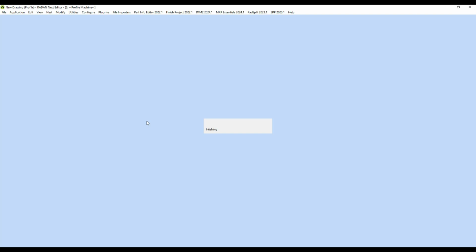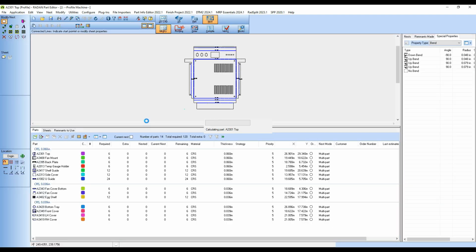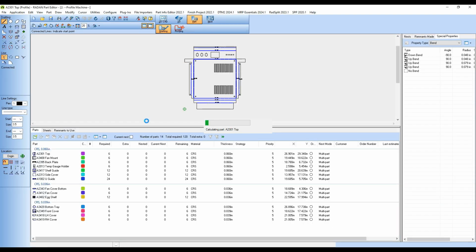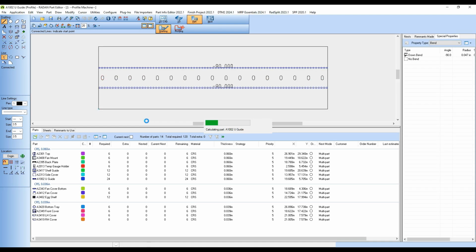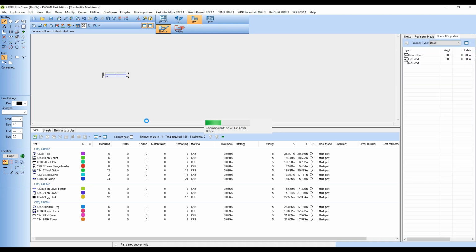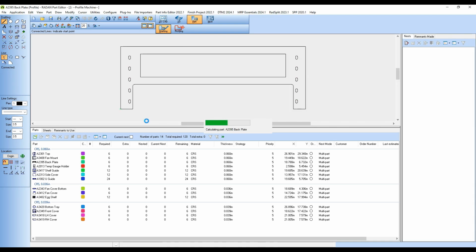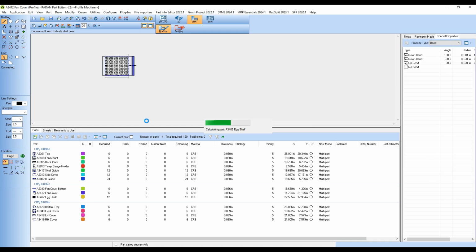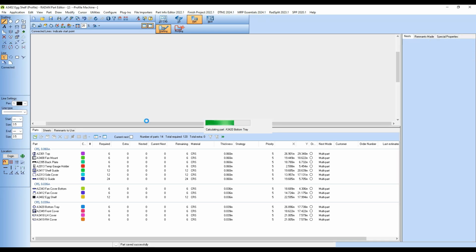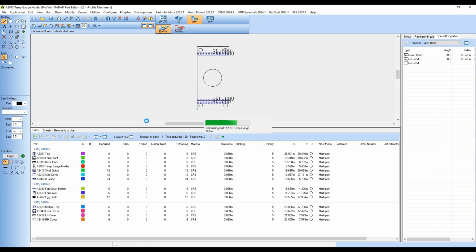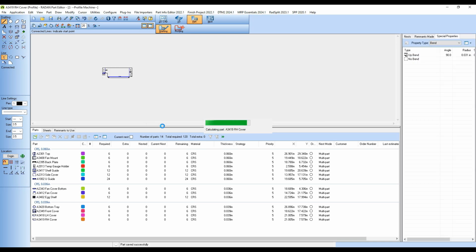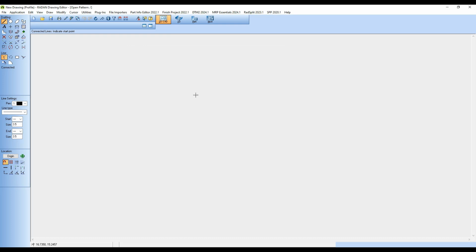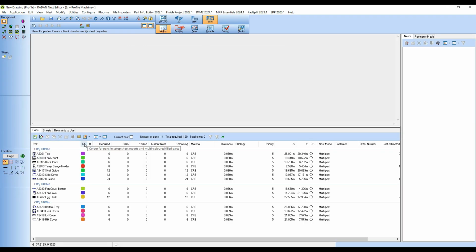In a moment here, we'll see the parts kind of flash up. You'll see them blank, and then you'll see a little flash, and then they'll have the toolpath applied, and then it's removed. It's going to process each of these parts in the same process, and then we'll nest up this group of parts to see what we get for our results. This is a very quick process. As you can see, we're almost finished with these parts. Now the last thing we need to do is simply just run the nester.